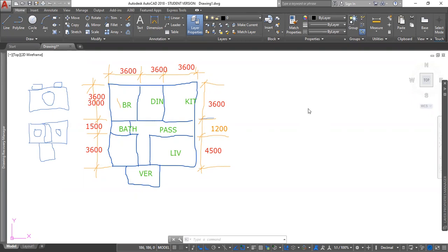At the end of this video, you should understand how to use the dynamic input. The dynamic input is a very useful feature. It is located down here. It's a rectangle with a plus sign. What the dynamic input does is allow the user to enter the X and the Y value for a point.